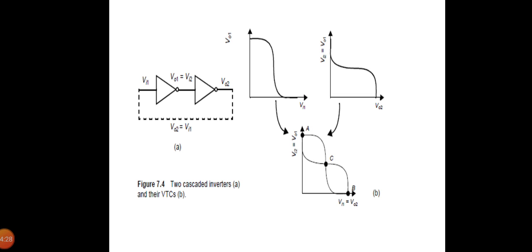Every deviation causes the operating point to run away from its original bias. The chance is indeed very small that the cross-coupled inverter pair is biased at C and stays there. Operating points with this property are termed metastable. On the other hand, A and B are stable operating points. In these points, the loop gain is much smaller than unity. Even a rather large deviation from the operating point reduces in size and disappears.